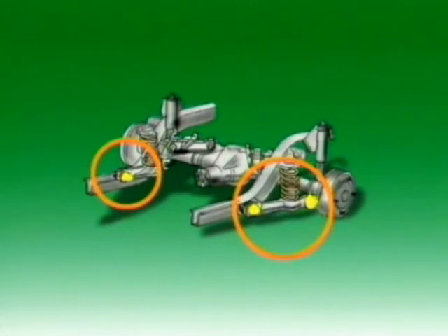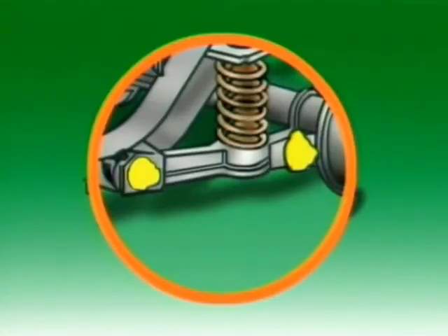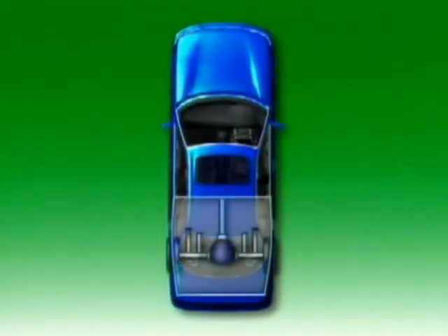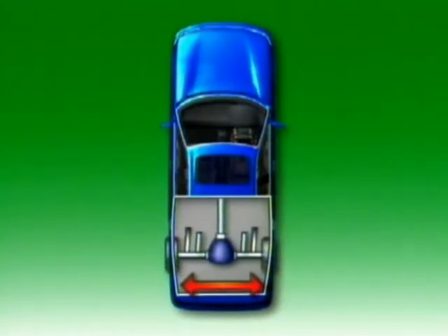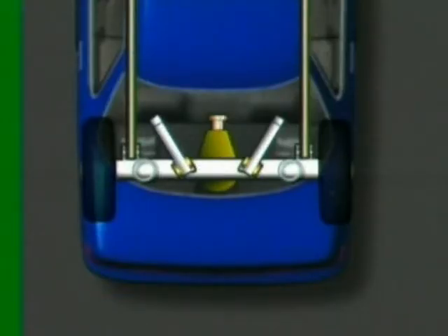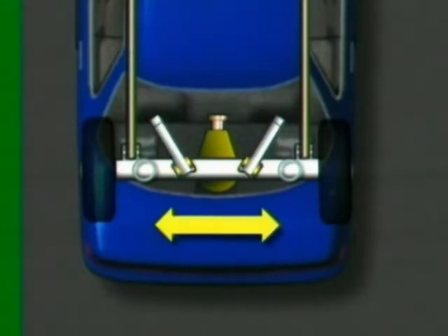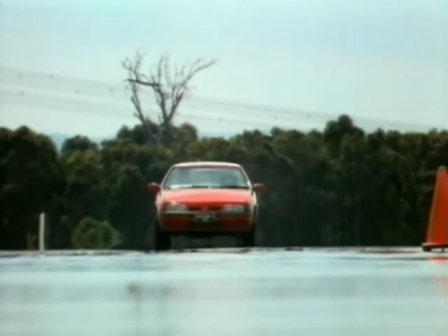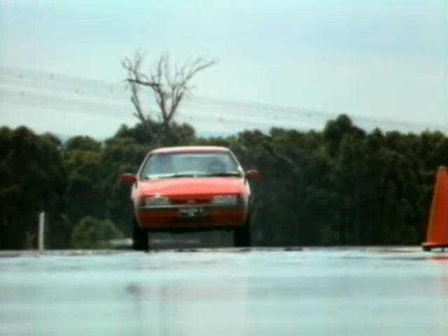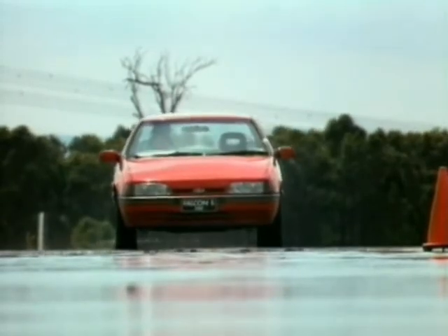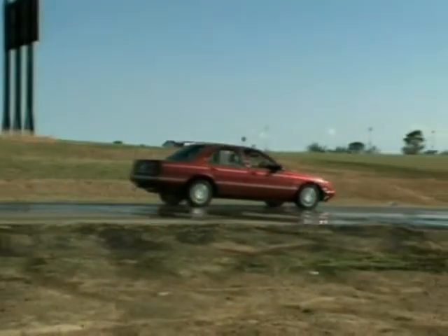They have flexible rubber mountings at each end where they locate on the axle housing and on the chassis frame. They would allow the axle to move laterally if it were not restrained. Any such movement has to be controlled to keep correct alignment with the front wheels and the vehicle frame. This suspension system uses angled upper control rods to limit lateral movement of the rear axle during cornering. They also absorb the torque reaction forces, which limits rear axle windup during accelerating and braking.